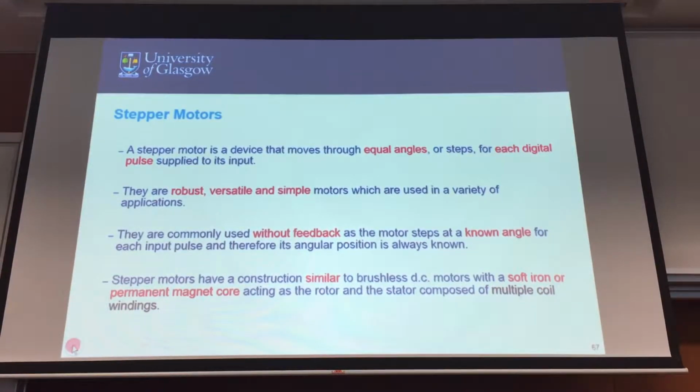We all thought a motor would just rotate, yeah, but there's more than that. If it's just rotating continuously, you have it for a certain function. But if you want to rotate it to a certain angular position, then you should be looking at a stepper motor. Then how to choose the correct stepper motor.